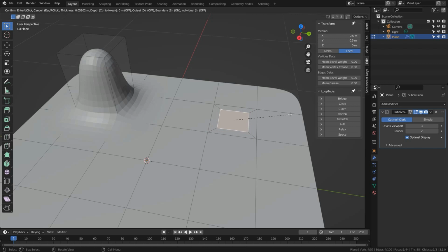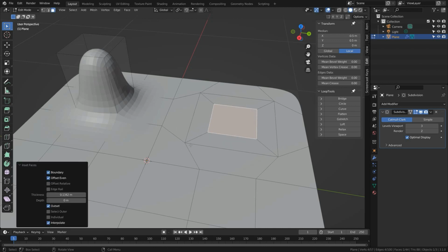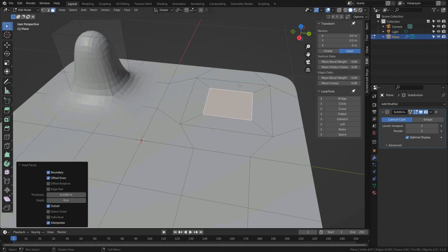Now because this makes our face a little smaller than the other one, I'm going to press O on the keyboard to change it to an outset, which is largely ignored and very much underused in modelling. It's a very powerful part of insetting when designing and modelling anything, and in our case we're using it to keep our extrusion exactly the same size as the other one, and at the same time we're deciding where the curvature up into the extrusion will start, and we've pushed the 5-spoked pole onto the flattest part of our mesh.